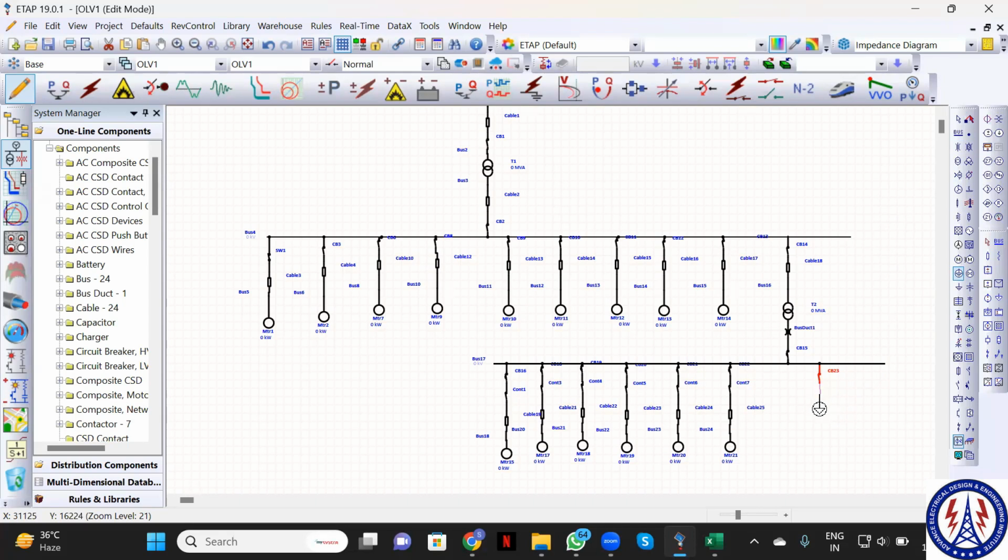What we are doing is adding all the kilowatts for the motors as well as the power loads and then creating them as a lump load. Suppose in my plant 50 are motors of 1 kilowatt and 50 are power feeders. So I will use a lump load, out of which 50% will be rotating and 50% will be static.